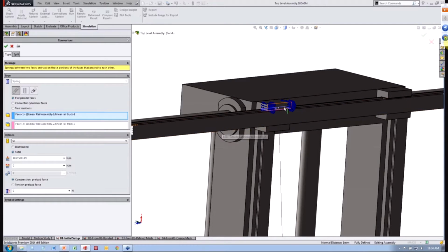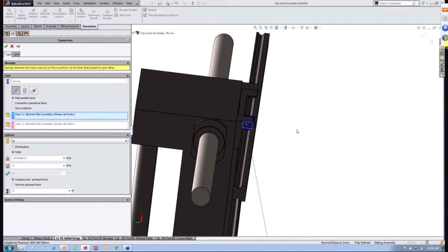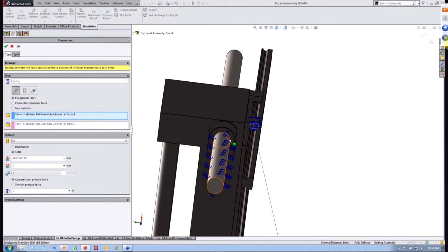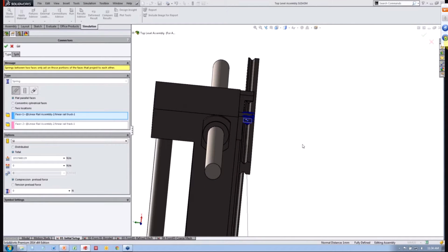They didn't want to provide a stiffness in the direction that the trucks would slide along the rails. That made sense, because there are ball bearings, and that allows essentially free movement along the rails, whereas the ball screws are what provide that rigidity, due to the bearings that act as threads that travel along the threaded rod.